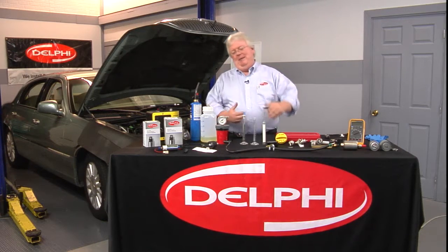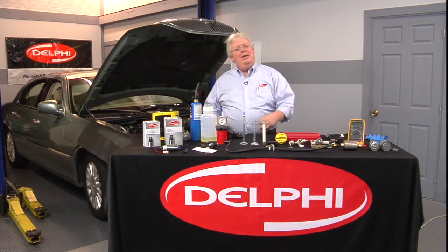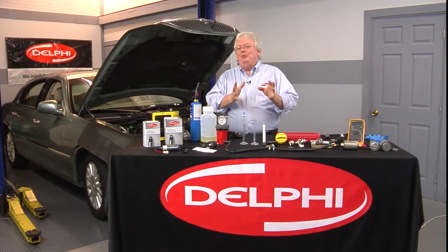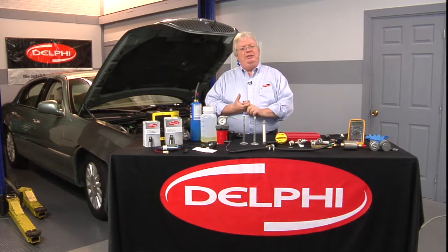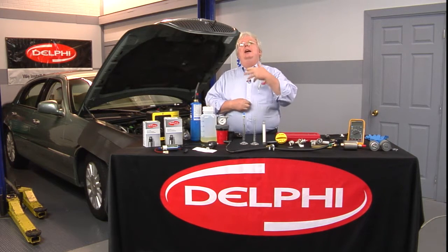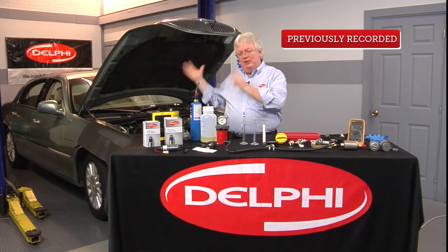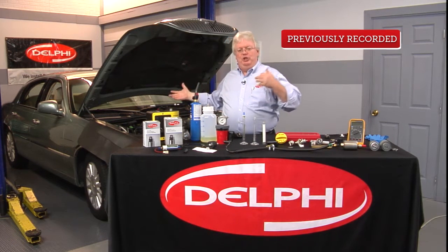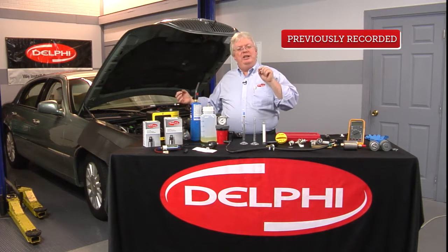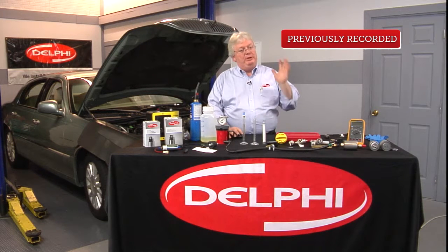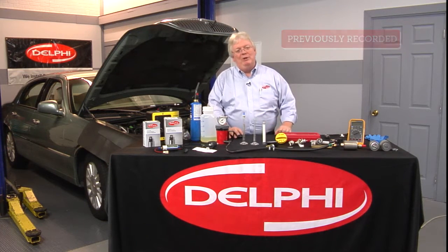If it's a calibration issue, keep that in mind. On the subject of calibrations, if you replace parts on the vehicle, say the fuel pump was bad with not enough pressure or volume, or I had a vacuum leak and replaced a gasket, and you do all those things and you still can't fix the fuel trim issue, always, always, always check for TSBs and updates and other sources of information to see if the manufacturer updated the software in the powertrain control module or ECM, engine control module, because you will not fix a software issue by replacing parts. So always look for updated software to fix fuel trim problems, because it's not just mechanical conditions, it can be software related.